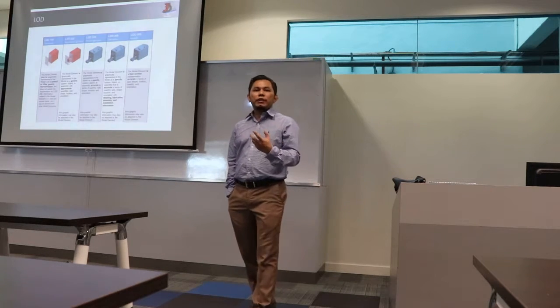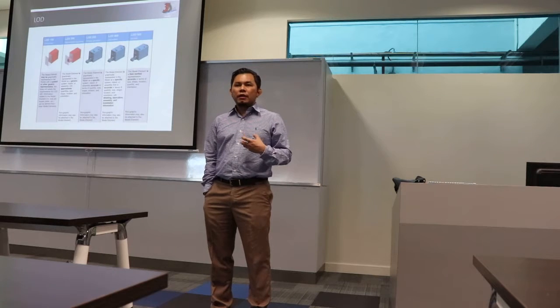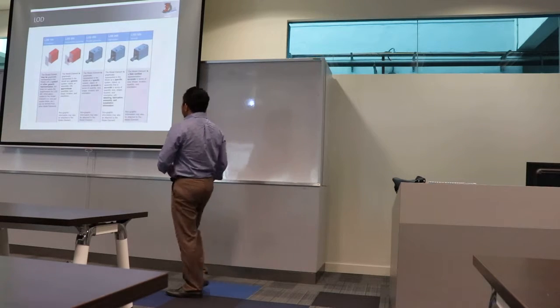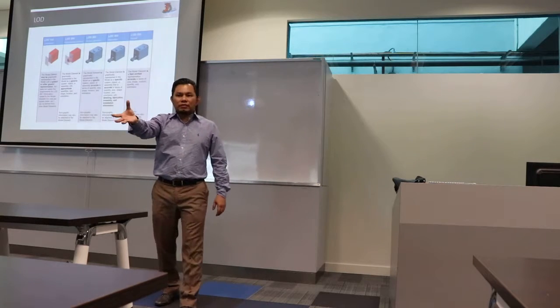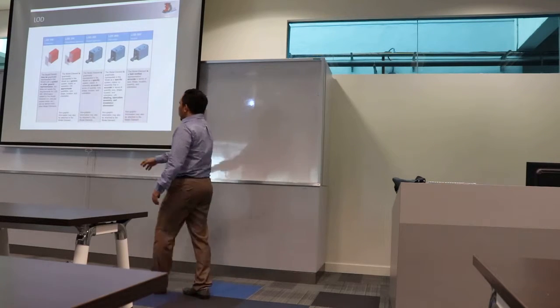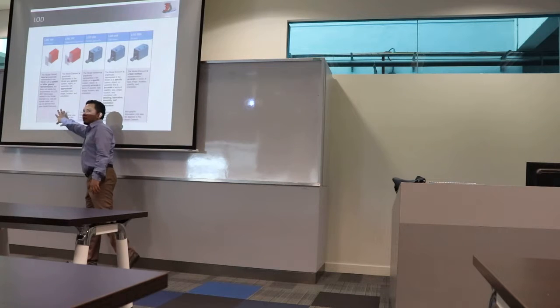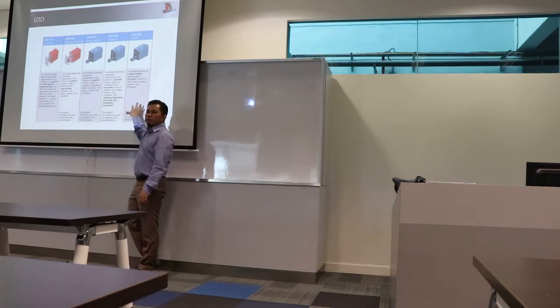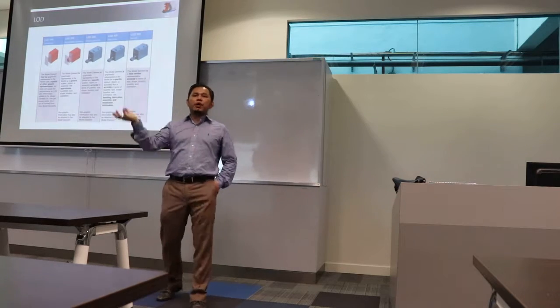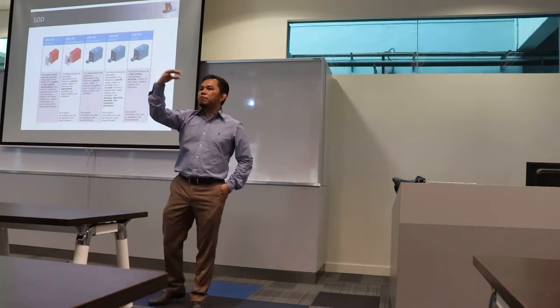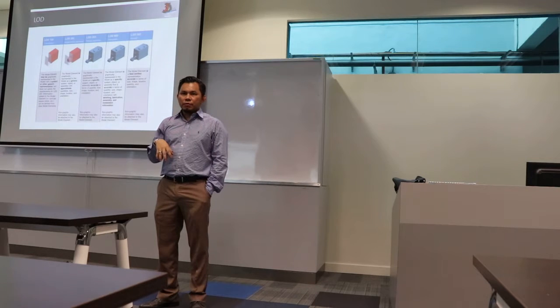So this is where the LOD 500 comes in. Now, LOD 400 still talks about what you plan to do on the construction. So all these are virtual basically. LOD 500 is really talking about validation of what you have built on site into the virtual information.